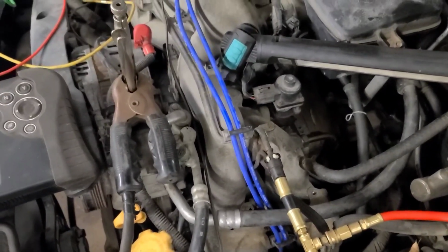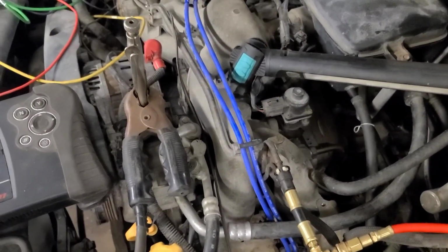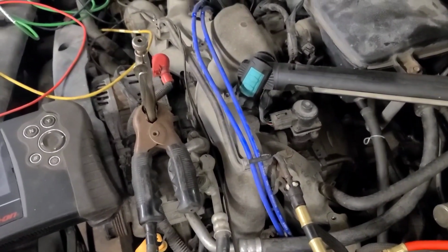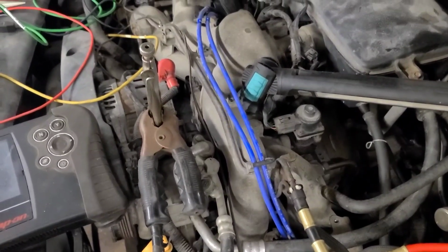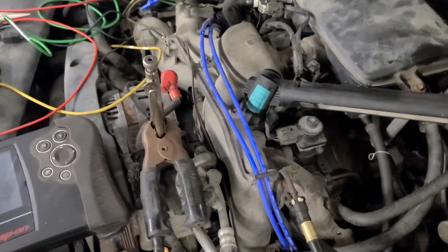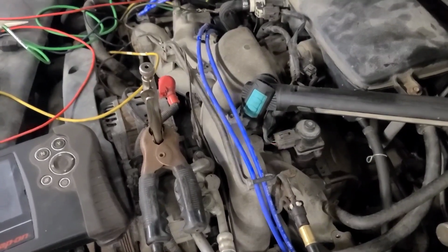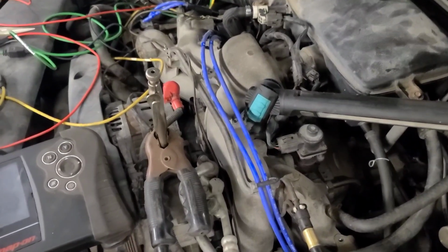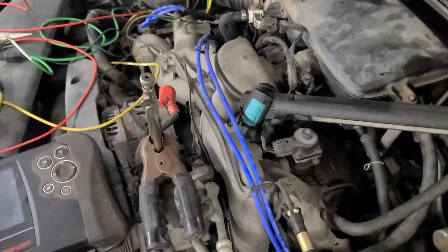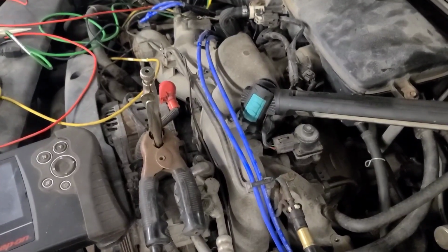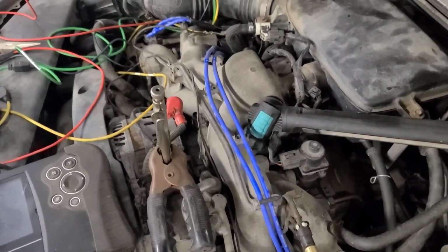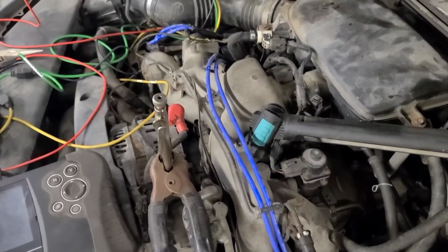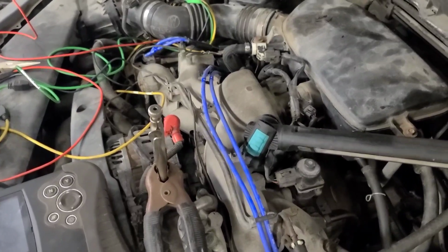Is there a possibility that we have a bad ground to that coil? It was going as high as 0.6, 0.7 volts. You're going to find out where those grounds are. Clean the grounds, because obviously when the system voltage is lower, everything is stressed even more, and it definitely drops to around 9-10 volts cranking cold. So I'm going to locate the grounds for these, and I'm going to clean all the grounds. I wish I had an OE coil to try on here, but I don't.